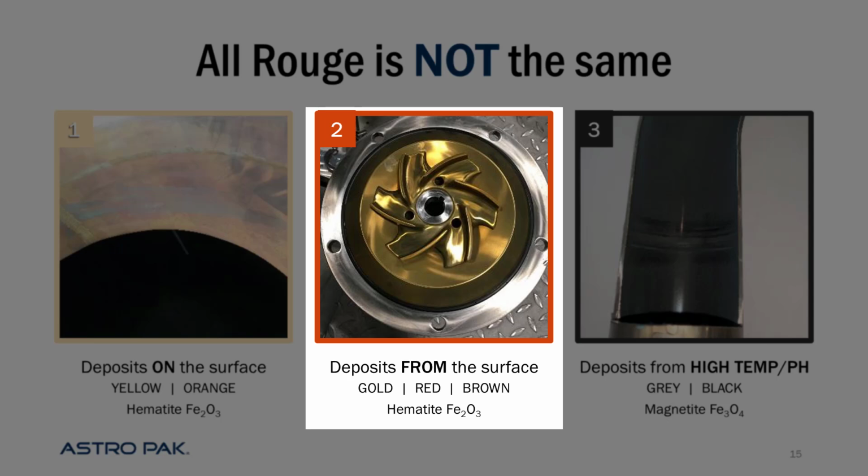So very similar acid chemicals can break this down. Type 2 rouge is a bit more well adhered to the surface though. And also notice that the colors aren't particularly strict. Type 2 rouge is typically going to be darker, but I see reds on both type 1 and type 2 rouge. I see any sort of color and any sort of brightness or shade.